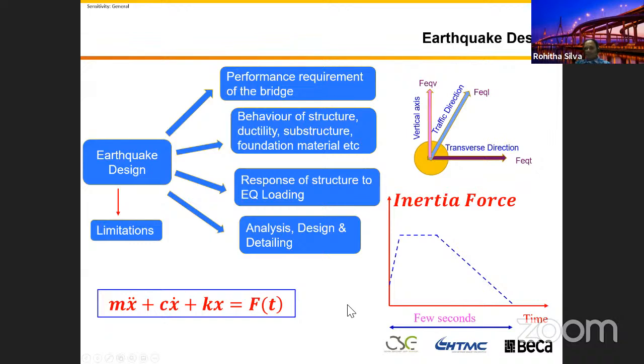Because the earth is moving, there is an inertia. If you intercept the wave energy with your structure, your substructure, that causes an inertia force induced into your structure. It could be a building or a bridge. We are working in three-dimensional space, so that inertia force will translate into a bridge as a force in the longitudinal direction, the transverse direction, or the vertical direction.